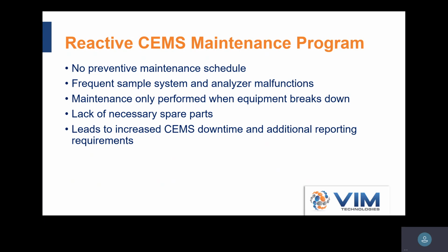There's a lack of necessary spare parts. I mean, if you don't have the spare parts, you can't make the required repairs. So having a robust spare parts inventory is essential to making sure that the system's performing properly. And then all of these lead to CEMS downtime.